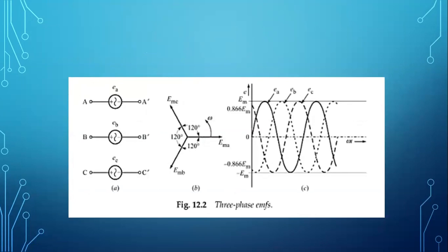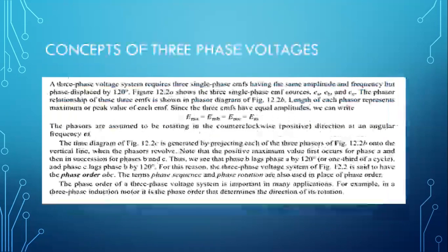So here basically my three phases are 120-degree apart from each other when I'm talking about a balanced three phase system. Okay, so we can represent them in polar form, that is magnitude along with its angle, and we can also use the J operator to represent any of these three phases, and we can have mathematical operations on them.